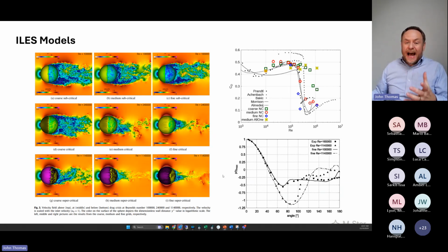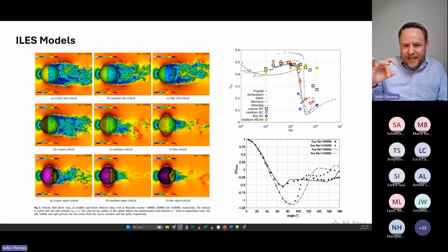What's neat about this is that because they're not adulterating the viscosity at all, they can capture physics that are very sensitive to Reynolds number. So if you're squeezing around with viscosity and trying to observe a function that is closely related to Reynolds number, the ground might be moving underneath your feet. It might be hard to pin that down. You need to use an approach that doesn't monkey around with viscosity.